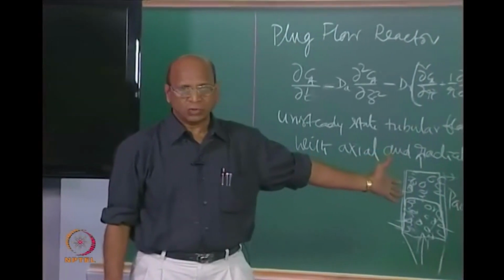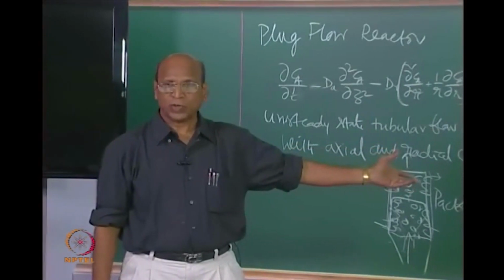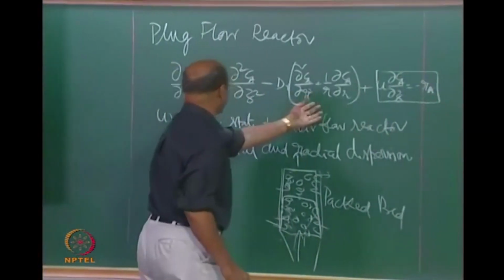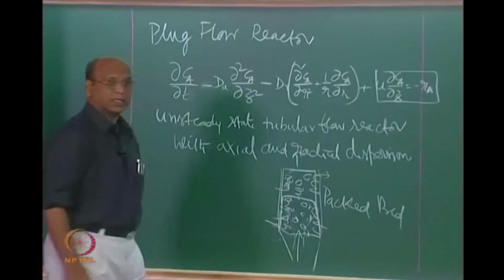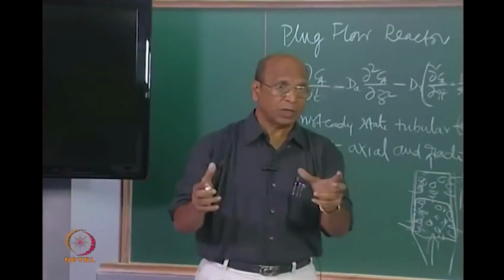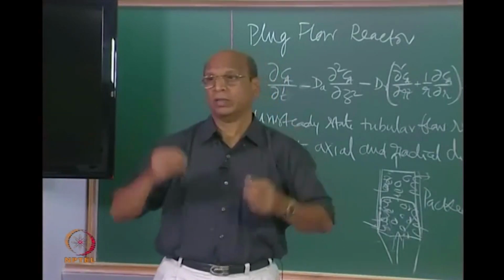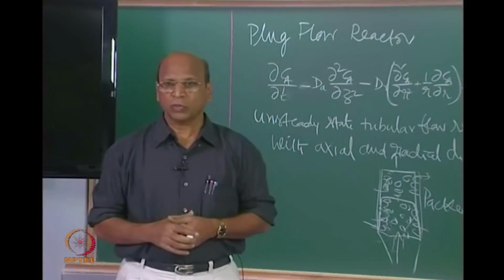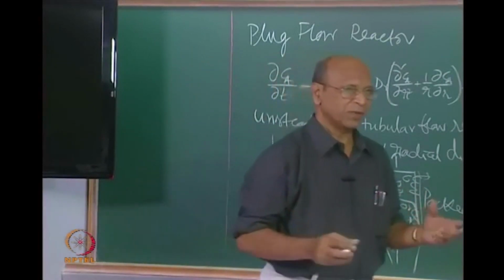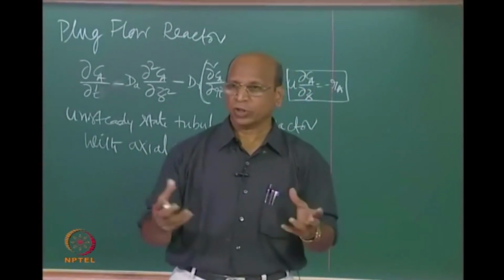Okay. So, you do not have an analytical solution for even a first order reaction there, right. You have to go for some numerical technique where you have to use delta R here, delta Z here, delta CA, delta T. So, finite difference methods, various methods are there, you can always see. You see, I mean how complicated the reactor design expression is the moment I go to the real world. That is why I want to be in Levenspiel's world. Levenspiel's world is an imaginary world, beautiful, very simple problems and also very nicely done, and with jokes and all that.